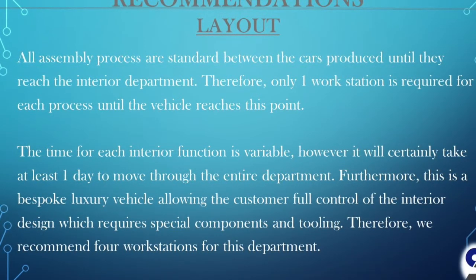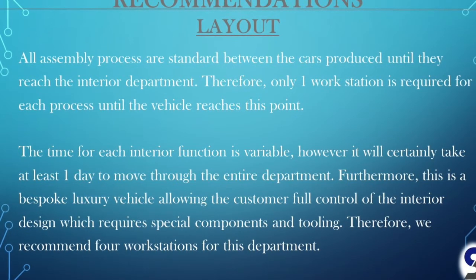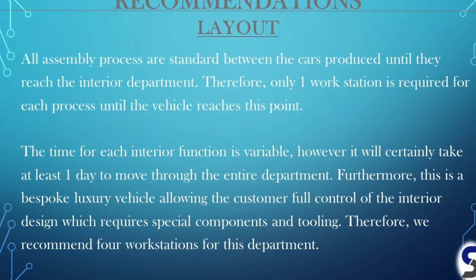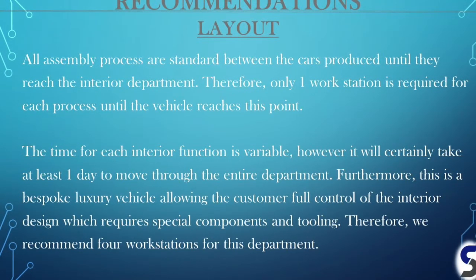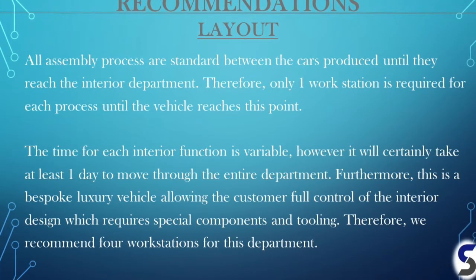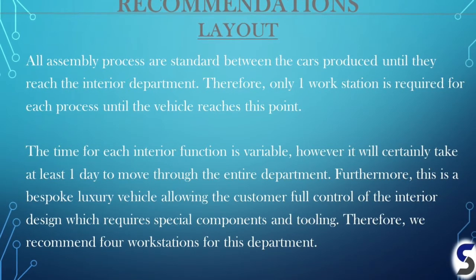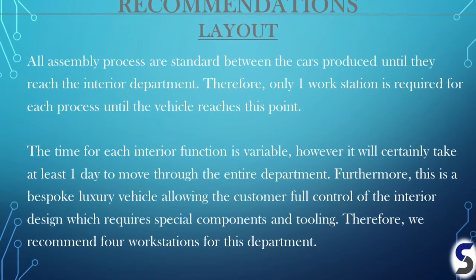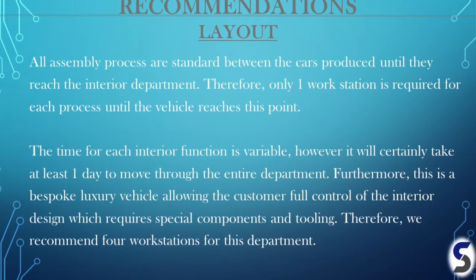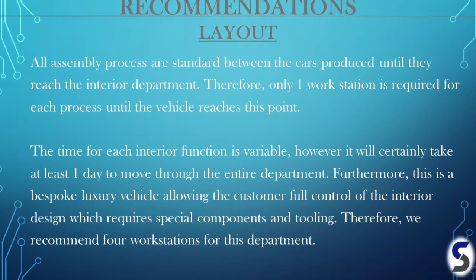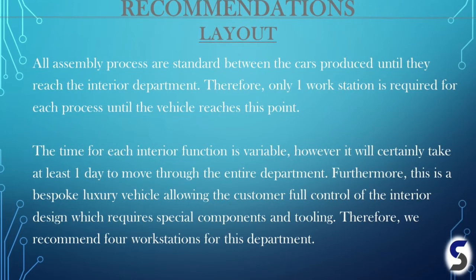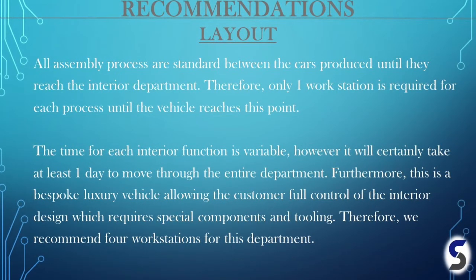We were able to determine our layout widths based on the allowance between columns of 25 feet, which also fits our requirement based on worker walkways of 3 feet, our 6.5 foot chassis, and our inventory size of 6.5 feet, as well as a buffer area around the chassis and vehicle for installation, and another 15% clearance. Our lengths were determined based on inventory sizes needed, how many machines would need to be used, as well as our clearances. Based on our takt times up to the interior stage, we found we would only need 1 workstation with 2 workers to meet our client's 400 car per year requirement 4 years into the future.